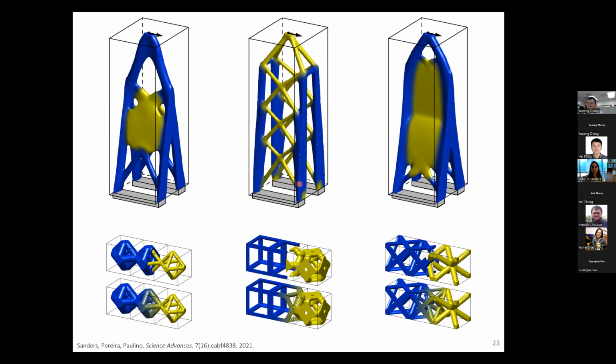Another challenge here is simply communicating the multiscale geometry to our 3D printer. So this is a complex structure, and we're going to embed these complex meso-scale features throughout, okay? And if we generate a surface representation or a triangulation of the multiscale structure, it leads to STL files that can be enormously large, especially if we want to scale our macrostructure geometry and keep our mesoscale features at the resolution of the printer. And so we want to avoid surface representations, avoid STL files, and figure out a new way to communicate with our 3D printer.